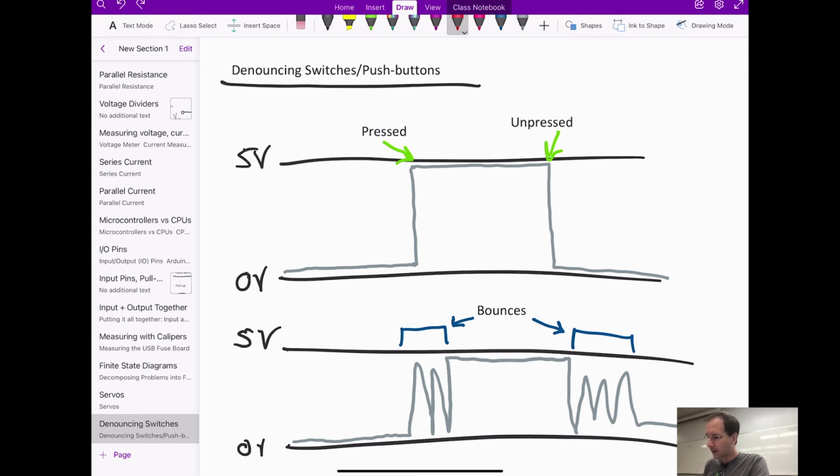But basically, to give you a sort of hint here, when you're talking about the button being pressed, once you register a press, for example here, you can sort of have a bit of a, for example, a refractory period or whatnot, where it takes it as pressed and then it can't be re-engaged for some period of time, and vice versa for the other side. Once it's been depressed, then there's some sort of refractory period here. And so the question is, how long is that period, right? And that's something that you're going to have to figure out empirically.